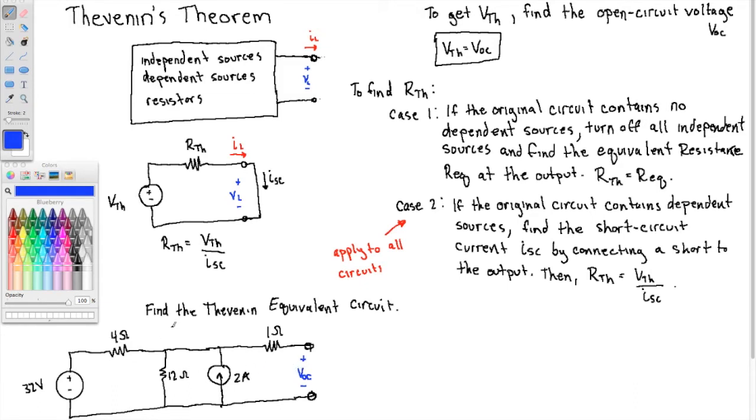So now I have to perform circuit analysis on this circuit to find that voltage. Anything that I've learned before I can apply here. So think about KVL, KCL, combining resistors. I can't really combine any resistors, but I will notice that mesh analysis is quite simple here. This guy on the right is not a mesh because of the open circuit. That leaves me with this mesh, but I know that that is 2 amps. And then I've got this mesh. So this is my unknown here. Let me use mesh analysis to find I1.